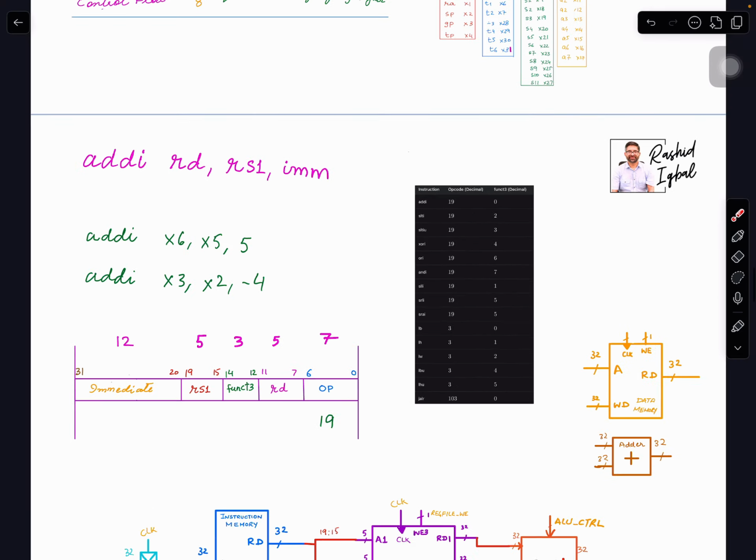And in total we can have in excess of 4 gig memory. That is 32 bits, and I'm assuming at address 0. How many zeros? 32 zeros. Or if you want to put it in hexadecimal, there will be 8 zeros. At that address, this instruction is stored.